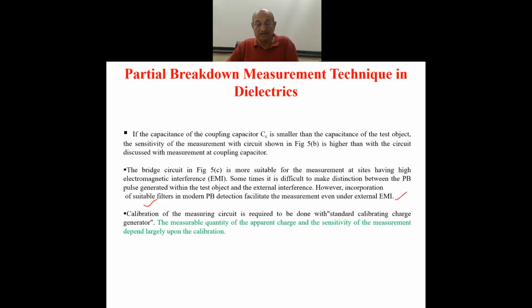With the help of filters, the detector is able to detect the external EMI and filter it, and only the pulses produced within the test object, which are also a kind of EMI, are detected by the PD detector.